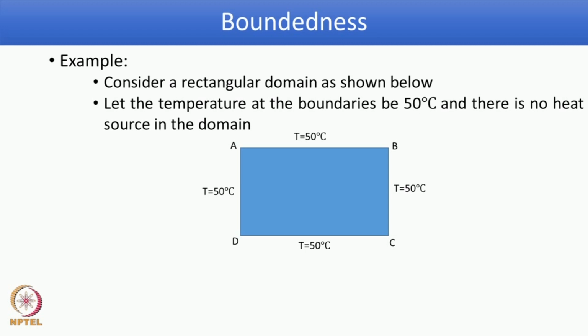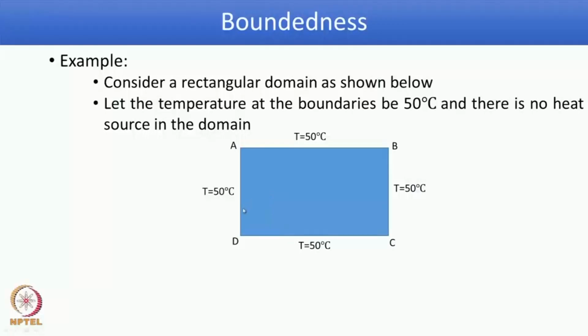You solve the transport equation for energy, which contains the temperature term. We already mentioned there is no source term inside the domain, or in the equation. In such a situation, when you solve the transport equation for temperature, finally, the temperature value should be within the boundary condition value that is specified.